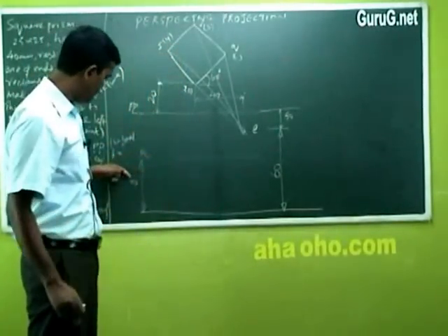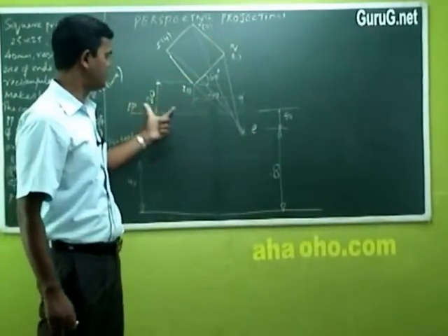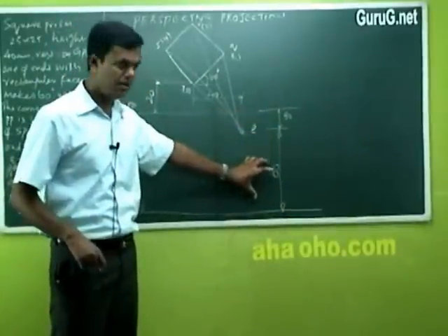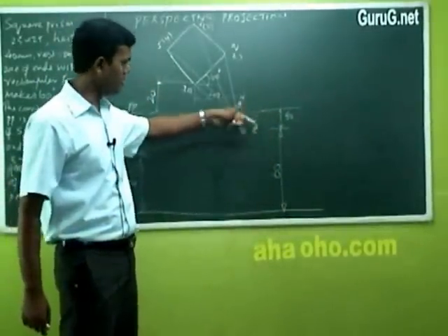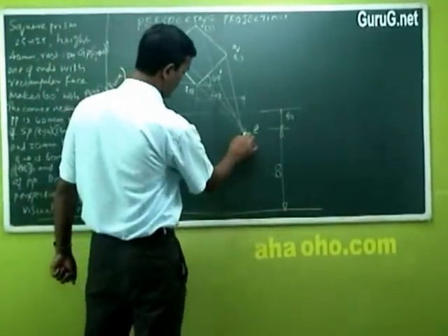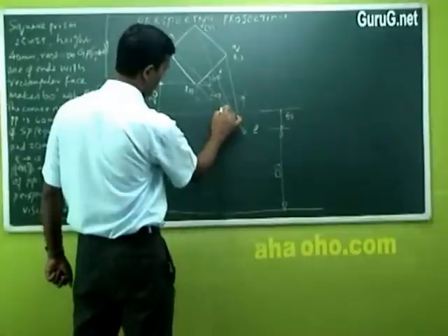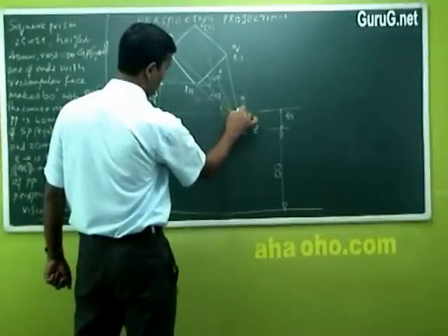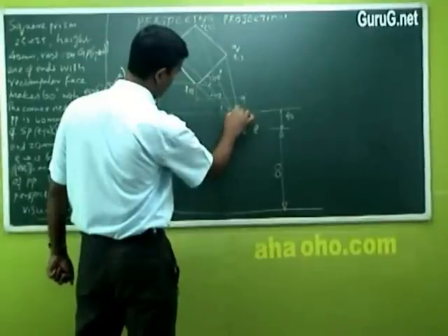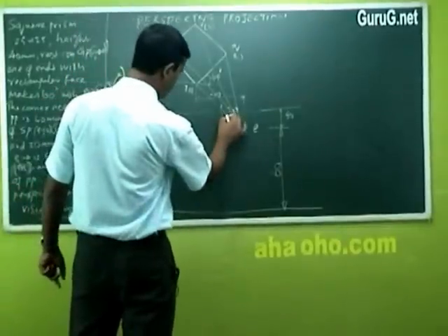In between, this above 40 mm comes here E, and above E, it comes here, picture plane 50. That's it. See, I have drawn 60 mm, such a big line, and 50 is so small, which cannot be explained that way. So this you have to indicate. Now what you do, from this point, wherever the point is cutting here, you mark it. It is 1 or 2 or 3, it's 4, 3 and 4. A proper marking you make. Fine.